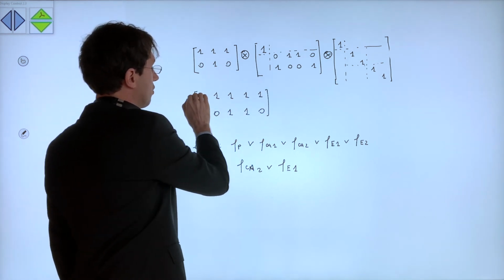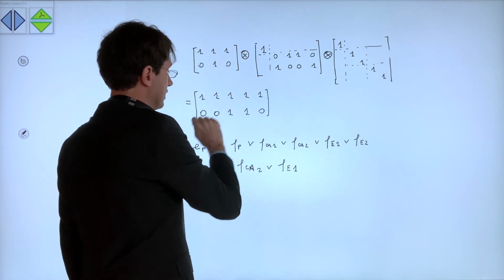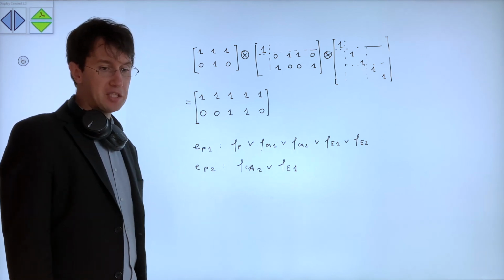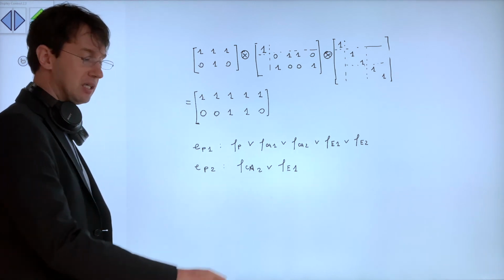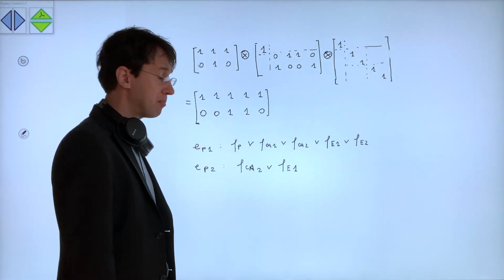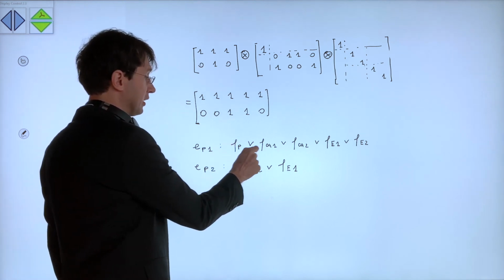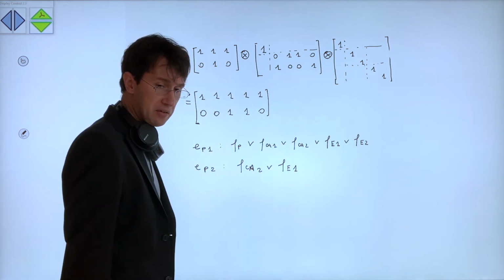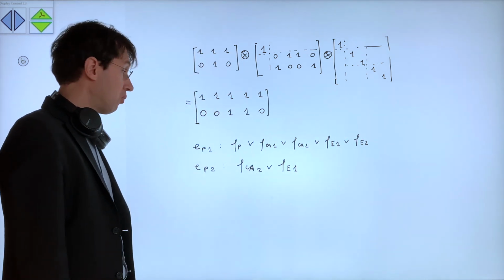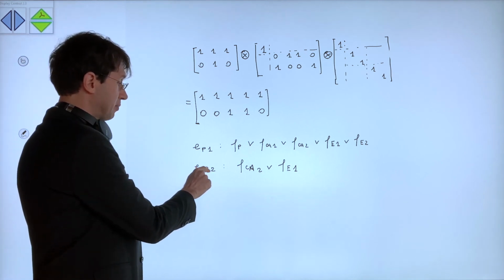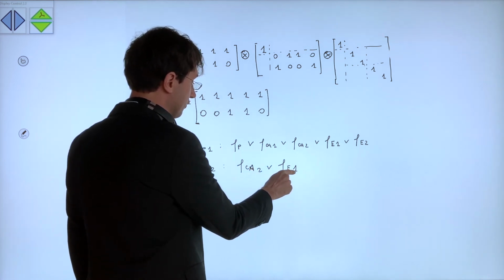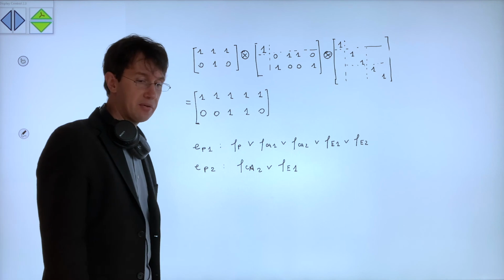So you have a row with only ones, and a row with some ones and zeros, which tells what? Something we could have imagined from the structure of the system. The first effect on the picker is caused by any of a fault on the picker, one of the 2 faults on the camera, or one of the 2 faults on the encoder. While the second effect on the picker can be caused only by the second fault on the camera or the first fault on the encoder.